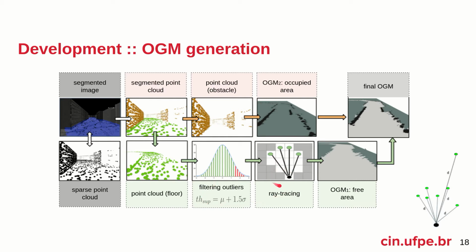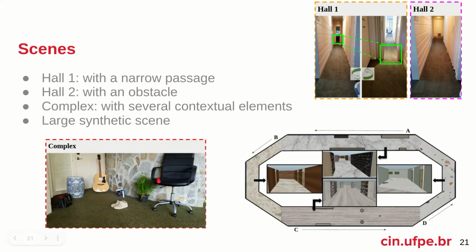The remaining ground points are used to apply ray tracing projected into a secondary OGM. This is a layer containing only potential free grids. The final map results from overlapping the two layers, and in case of conflict, the obstacle grid prevails for the sake of security.